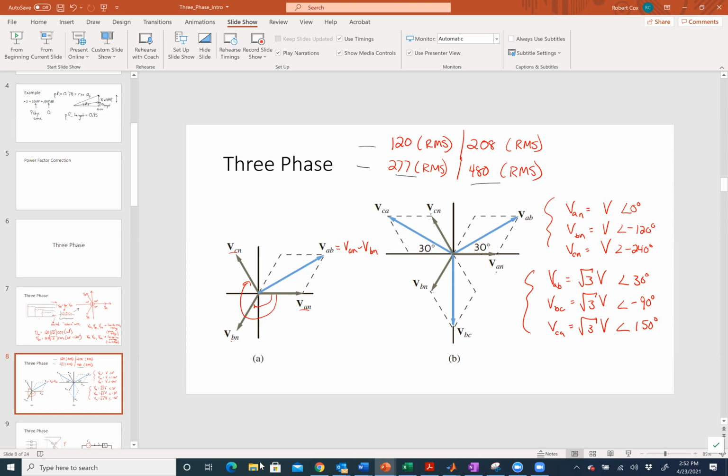Does that mean there's more voltage in an outlet in Epic than a regular house? That's okay. Yeah. So what it means is the main service coming into Epic is 480 volts line to line, 277 volts line to neutral. Epic, like any big building, then has transformers that go from the 480/277 to the 208/120. So the voltage at these outlets is 120, just like it is in your house. But there's going to be a transformer within the building that steps it down to a lower level. Right. Other questions?